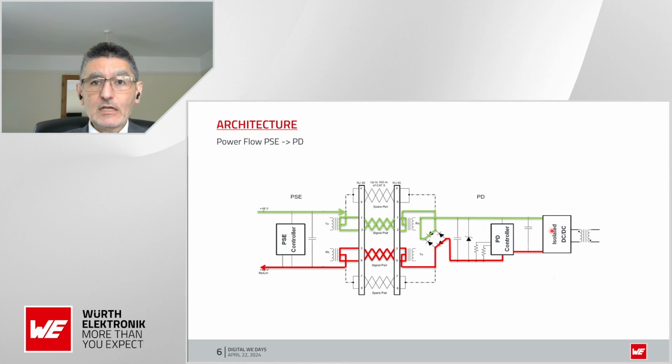to be isolated to maintain the requirements of the IEEE standard, which indicates a functional isolation of 1500 volts. Now, depending on the applications, I know medical applications, for example, they require higher levels of isolation voltage, which needs to be achieved again via the DC-DC converter.